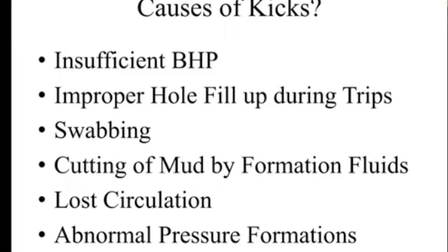When we are not pumping anything, bottom pressure is equal to static bottom pressure, hydrostatic pressure. When we start pumping, bottom pressure is equal to dynamic bottom pressure. When we increase the flow rate, bottom pressure increases. When we decrease the flow rate, bottom pressure decreases. So bottom pressure is not a fixed value. If at any point this pressure goes below formation pressure in a permeable formation, kick happens.